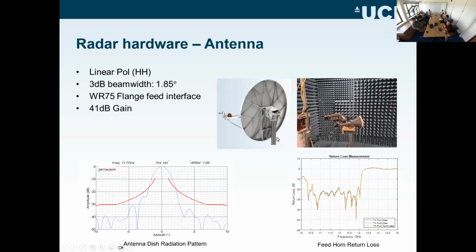And the last piece of the puzzle is the antennas. I mainly chose the frequency of the signal because of the commercially available parts. As you know, wide bandwidth also comes down to what parts are available. Because of the high gain needed, I realized that the band we chose falls into a popular SATCOM communication link, Ku band, which is the downlink of SATCOM communications. The dish antennas have quite a high gain and linear polarization, and because of the offset feeding mechanism, they have a nice symmetrical radiation pattern within the 3D beam.